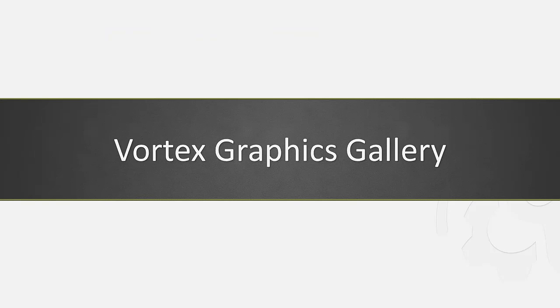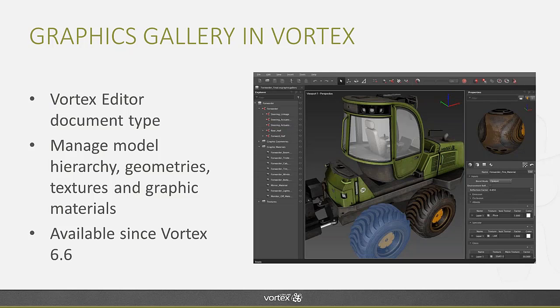Before we move on to the process of importing a model and creating graphic materials, I'd just like to talk about what the Graphics Gallery is. So it's a Vortex editor document type. It's on the same level as the assembly or as the mechanism. So it's a document type you can create in the Vortex editor and then connect with other parts of your simulation. It allows you to manage model hierarchy, so that is the graphics node, but also the geometries, graphics geometries, the mesh, textures, and the graphic materials used by your simulations.